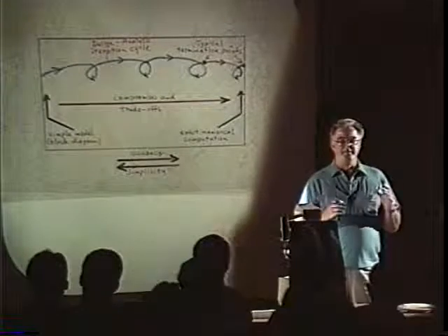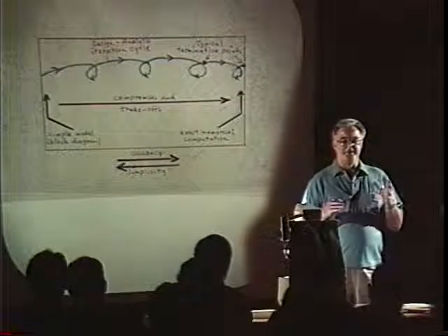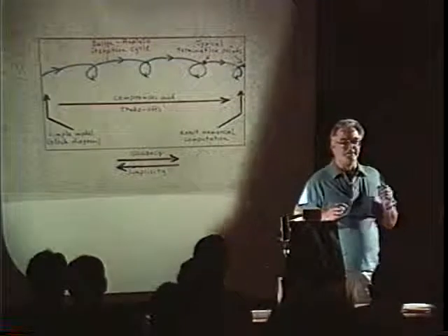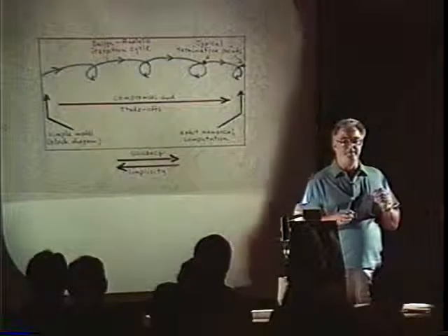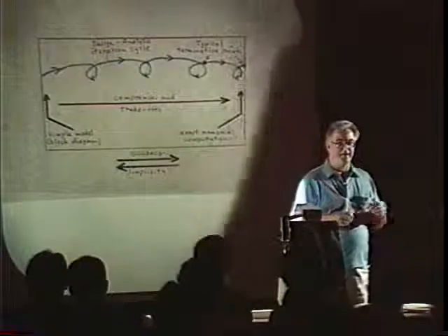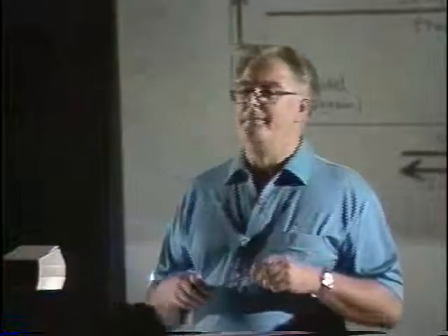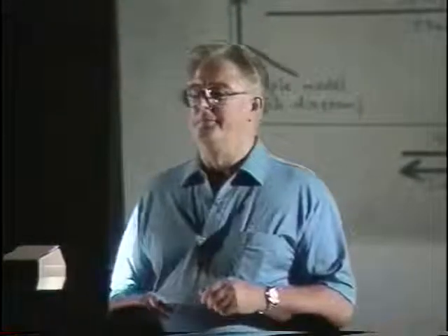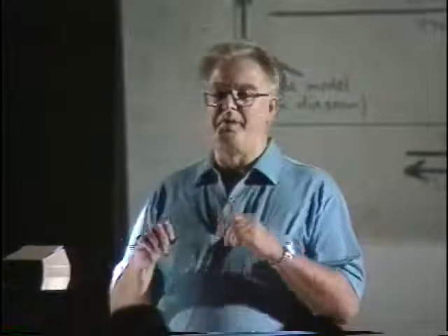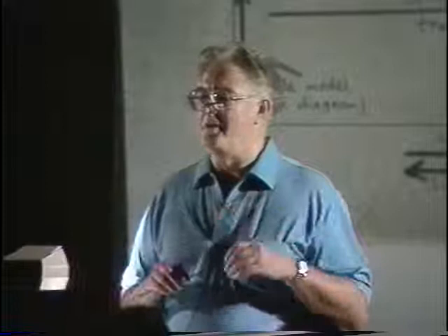There's the tolerance of the components that you have to work with, and that's taken as a given. That's part of your input information. Components are plus or minus 10% or whatever the number is. The other place that tolerance comes in is in the specification, the answer, because the specification also has to be subject to tolerance limits.